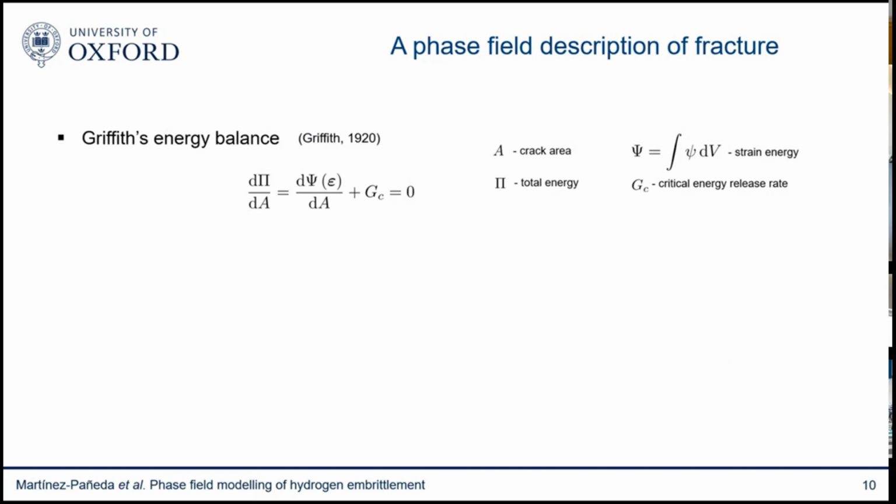And Griffith was the father of fracture mechanics, and he postulated this energy balance that became what we then later use for stress intensity factors, following the work of Irwin and so on and so forth. So this is the foundation of the field. Right? And the foundation basically is nothing but an energy balance resulting from thermodynamics.